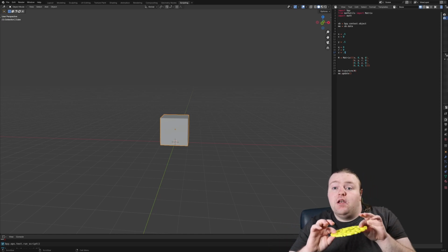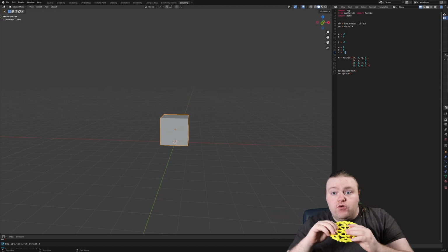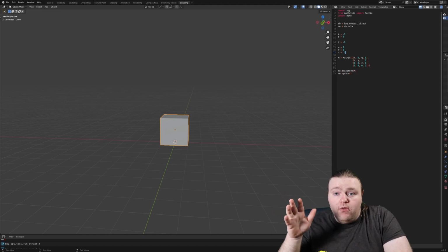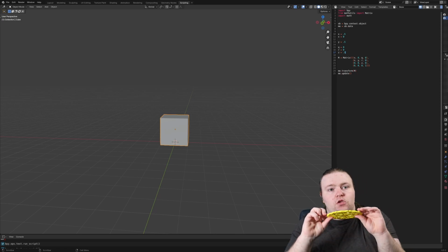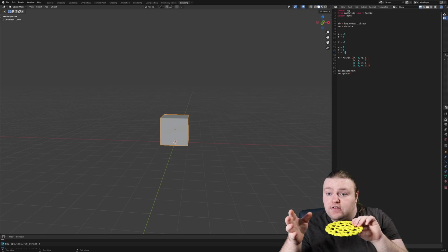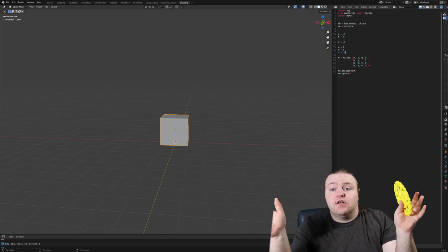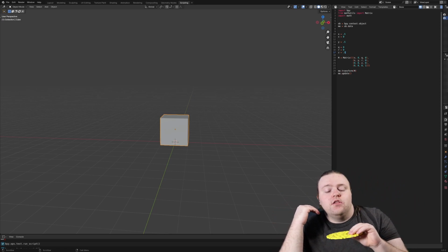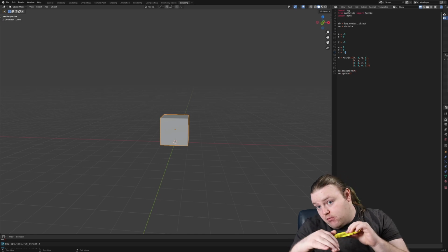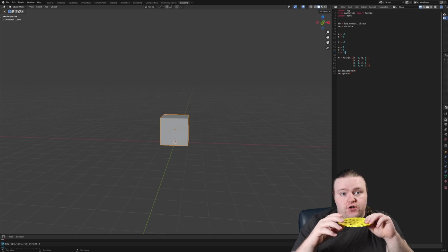There's nothing wrong with it but scale. So y can either be 1 if you don't want to include scale, or you can find what y is for your printer, what the scale is, to be able to correct for scale problems that is holistically inclusive. It includes the scale of problems with the stepper motor in the axis and shrinkage.